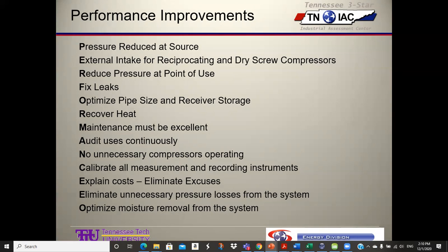Audit uses continuously. What are we using air for? Do we really need to do that? No unnecessary compressors operating. Calibrate all measurement recording instruments. Explain cost. Eliminate excuses. That's a good one. Eliminate unnecessary pressure losses from the system. Optimize moisture removal from the system.